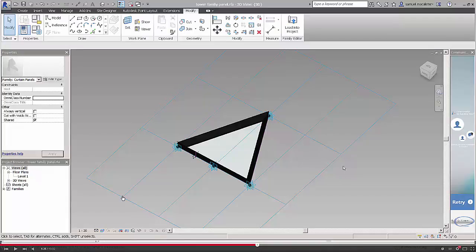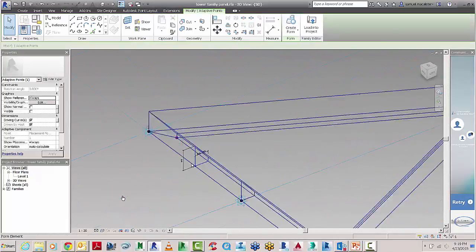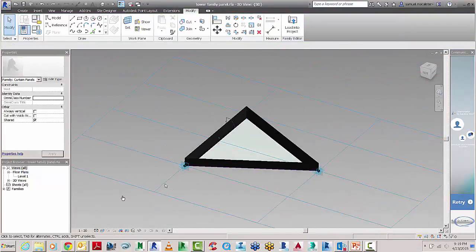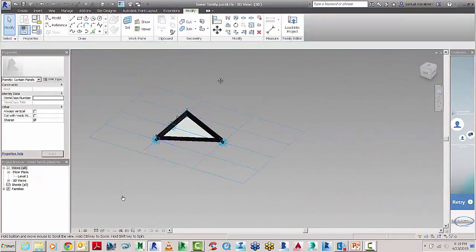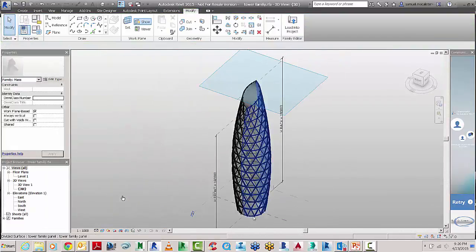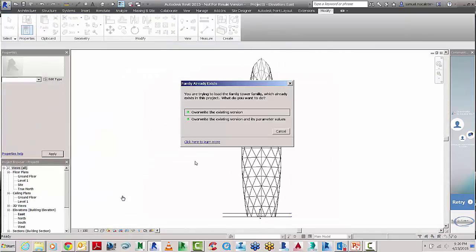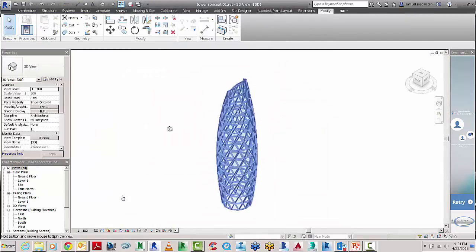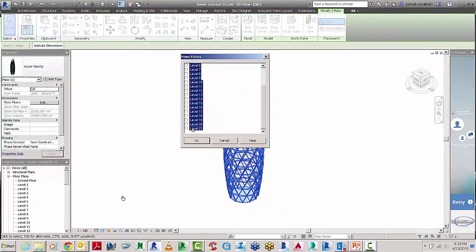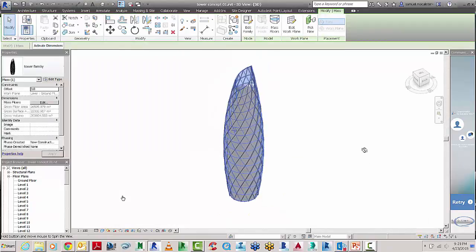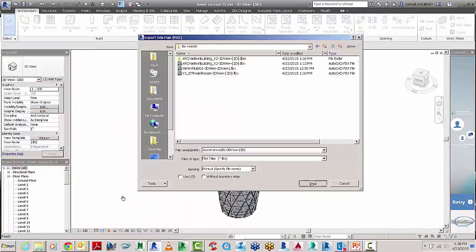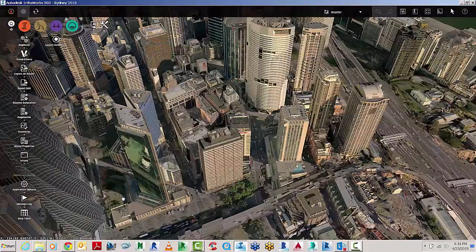And then finally, I just want to touch on the Revit workflows. So in this case, if you're designing a tower in Sydney, it needs to be pretty sharp, quite prestigious. It's going to be part of an iconic city front. So we're going to do this conceptual adaptive component model where we're doing a curved facade, and we've got this adaptive component that adapts to the shape that we've modeled in Revit. A lightweight model, doesn't have to have a huge amount of detail. We're just looking at it from a planning perspective.